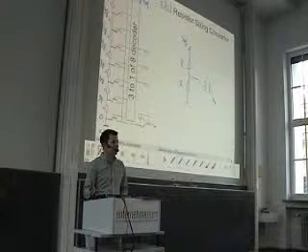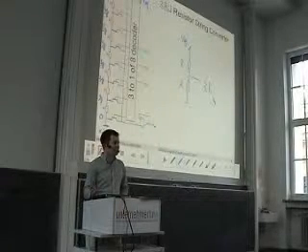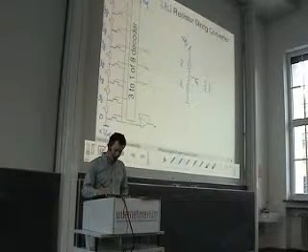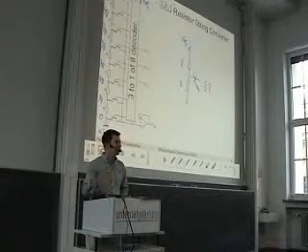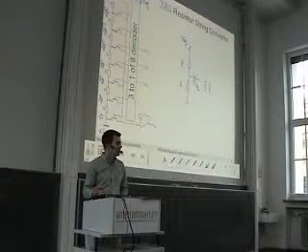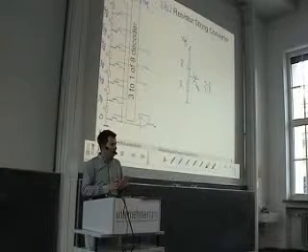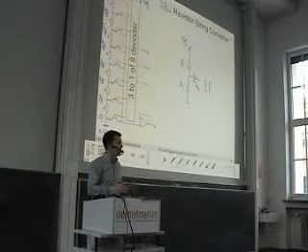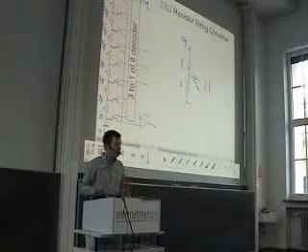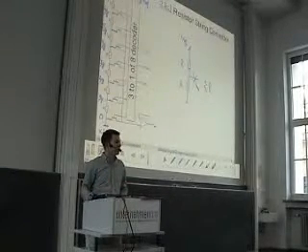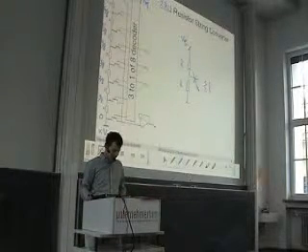Is this valid all the time? No, guys, okay? This is only valid if no current is flowing here. We say if the voltage divider is not loaded. So the voltage divider is a good way to generate voltages or derive fractions from a reference voltage. However, we have always to assure that no current is flowing or only a negligible current is flowing out of the voltage divider. Okay.